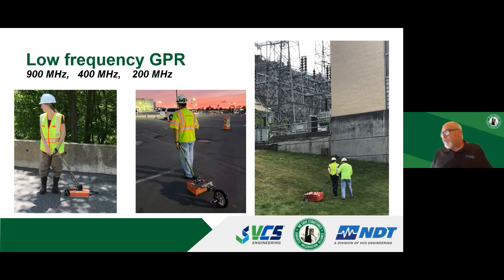In the middle is the 400 megahertz. That's our workhorse for locating utilities, sinkholes, whatever the case may be. And that orange antenna is getting a little bit bigger as the frequency goes down. And on the right image is the 200 megahertz antenna. That's even bigger. It has a little more penetration, but you lose resolution. The deeper you get information, the less clear it usually is. And sometimes we may use 2 or 3 different antennas to get the full picture of the subsurface conditions. So again, often one antenna is not sufficient.